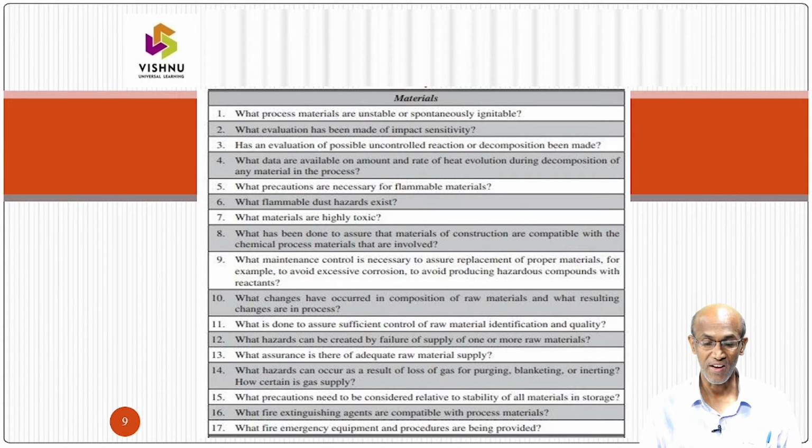What hazards can occur as a result of loss of gas for purging, blanketing or inerting? How certain is the gas supply? What precautions need to be considered relative to stability of all materials in storage?